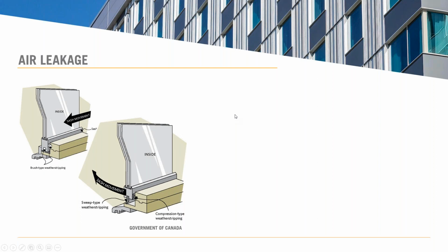So first of all, one of the key principles for high performance buildings and building energy performance standards is air leakage. How the windows play into that is how they seal within the system. So you're going to see fewer and fewer sliding windows possible on higher performance buildings because that sliding seal relies on a friction seal there. It's just not as good.